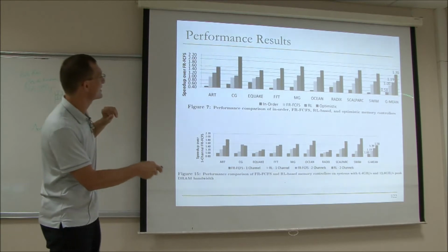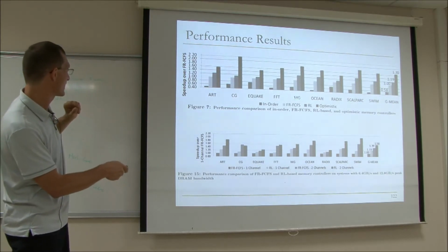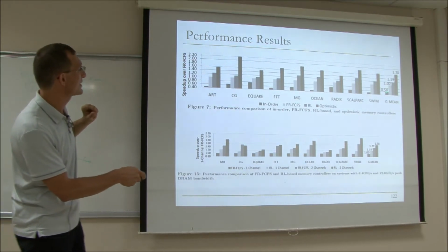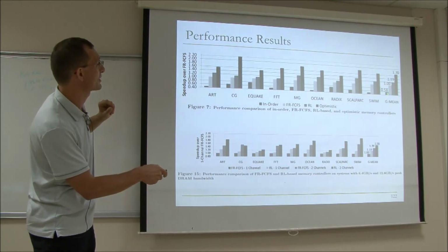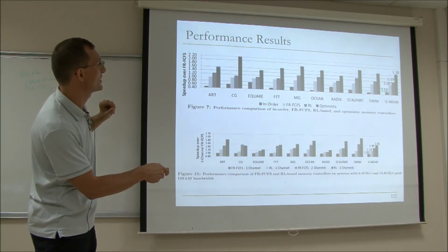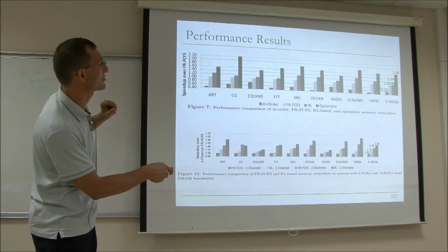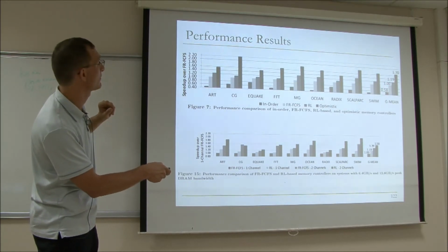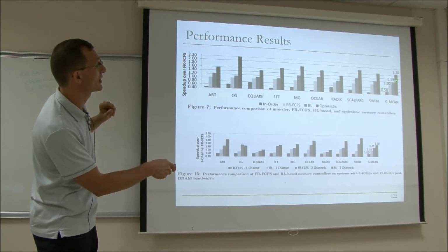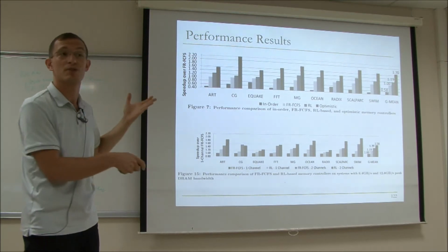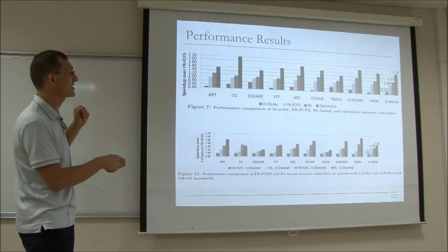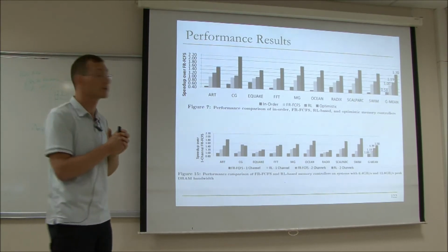So if you look at this, these are parallel applications over here. And this is the in-order, first-come, first-served scheduling policy. That actually performs pretty badly. This is the row hit first scheduling policy, which performs more than 40% better than in-order, first-come, first-served. And this is reinforcement learning-based scheduling. You get about 20% better performance on these parallel applications by maximizing data bus utilization.